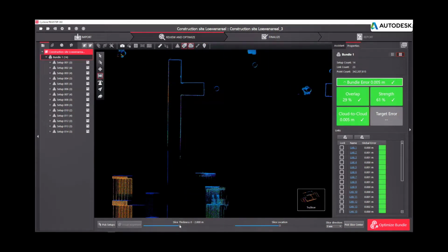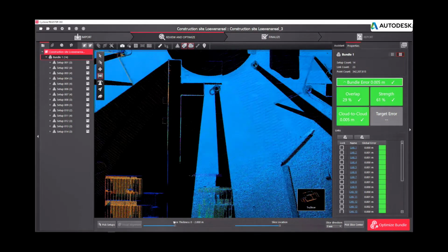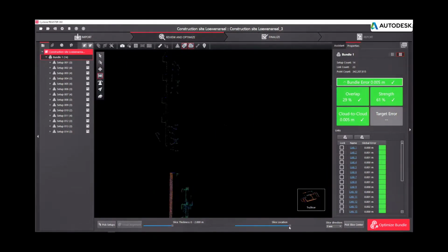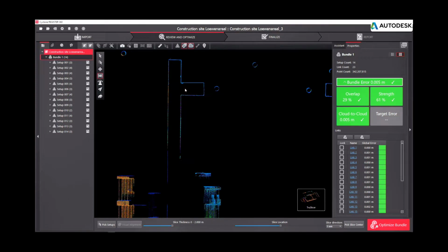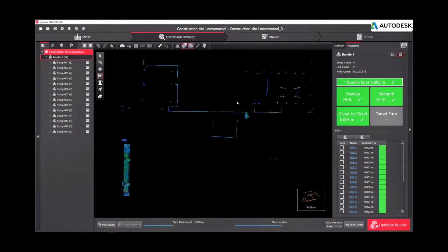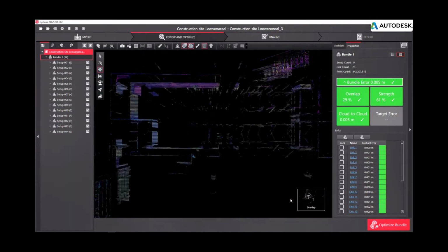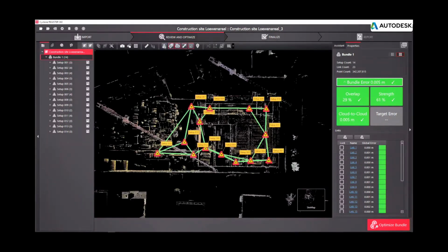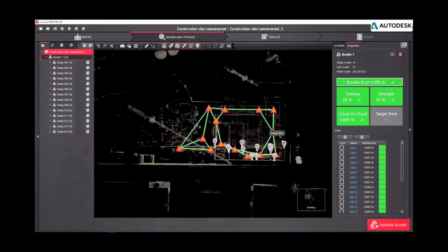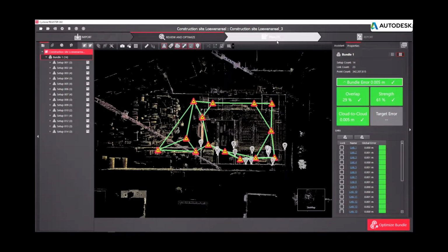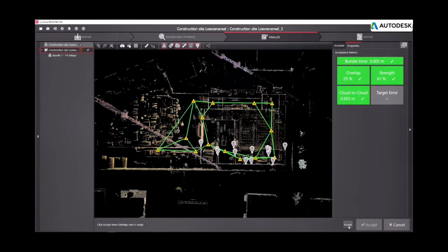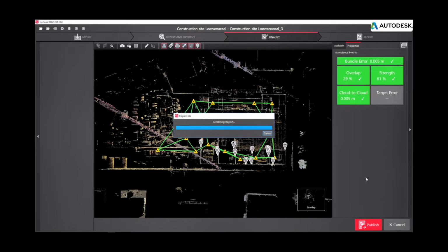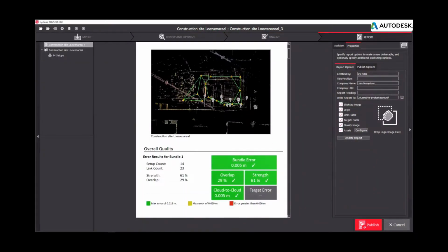We're now in the True Slicer. QA tools are a big piece of Register 360. This is our True Slicer. You can interrogate the cloud and look at a slice level to check your registration, and then we can provide some other miscellaneous visualizations here. As I said, we're bringing in this data, creating our registrations, checking our registrations, and moving through the workflow. Now I'm creating my registration report.